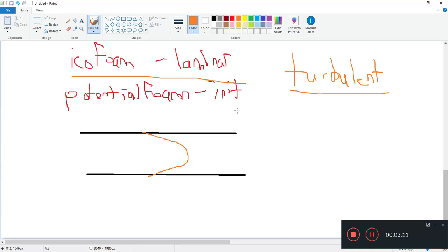And I want to introduce us to something called pisoFoam, which is the turbulent equivalent of icoFoam, to help us sort out this problem. And that's where we are headed. We want to head during our next few videos to do turbulent pipe flow. This is the most simple case. Alright, turbulent pipe flow.